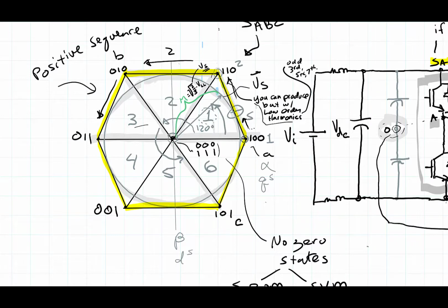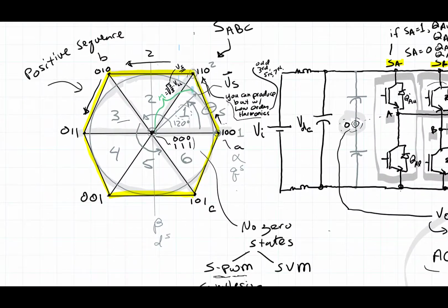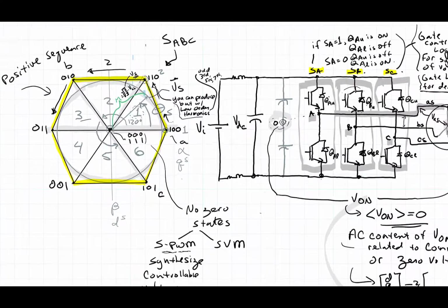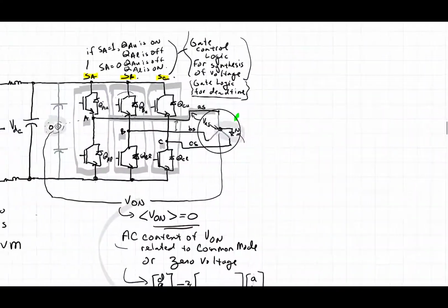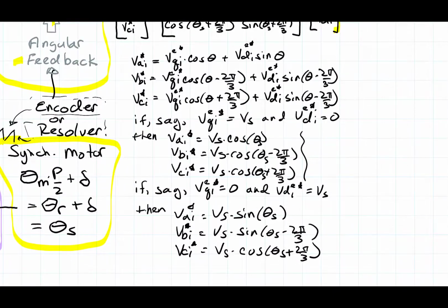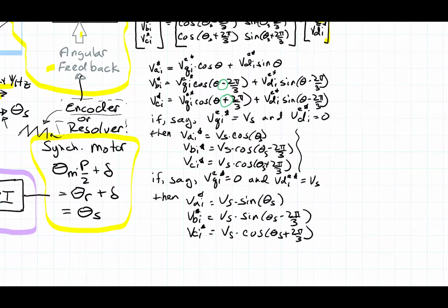And that actually relates to the direction the motor's going. If we wanted to go in the opposite direction, it would be effectively a negative sequence. What we're doing when we go the opposite direction, and I'll show you that up here, if you go in the opposite direction, you're going to take these signs and flip them. So the B and the C, you make a positive here and a negative here, then that would mean you're going the other direction.